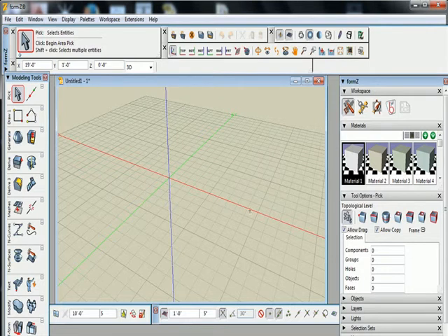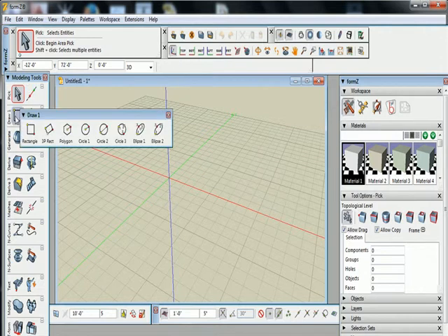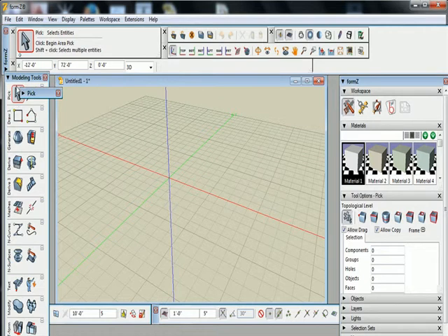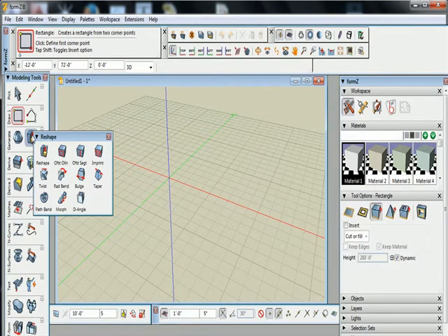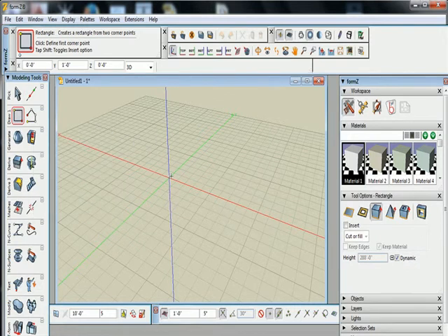So in this area, we are going to draw our first bottom cube. Okay, and that bottom cube is actually 18 feet by 18 feet by 18 feet. Now there's a particular way that FormZ would want you to input that specific dimension. First of all, go to the Draw One tool right under the Pick tool and go to Rectangle. Select that tool and then hover over your center, the origin point.